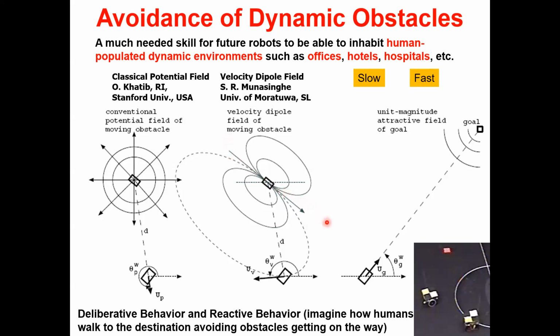So if you know the direction of the robot, you can generate these field lines, and you can mathematically define them as ellipses, right? Because everything has to be analytical. So the field lines should be mathematically defined. We use ellipses because there's no need to use exact magnetic field lines, because this is not a magnetic field problem. This is obstacle avoidance. So you could have taken anything that is reasonably good. So we use ellipses, like that. The elliptical field lines are like that.